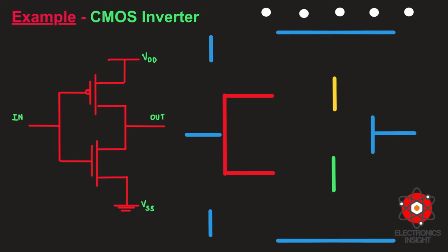So now, as per the first rule, we need to fix the VDD and VSS layers, leaving sufficient space between them. And I've also mentioned that since both of these VDD and VSS layers are going to be metallic layers, we again use blue color. And next, the second step, is where we need to fix the N diffusion and P diffusion layers. For the N diffusion layer near the NMOS transistors, we use green color, and for the P diffusion layer I have used a yellow color. Okay, so now these diffusion layers are generally nothing but your active areas where you are going to take or give interconnections with your polysilicon layer.